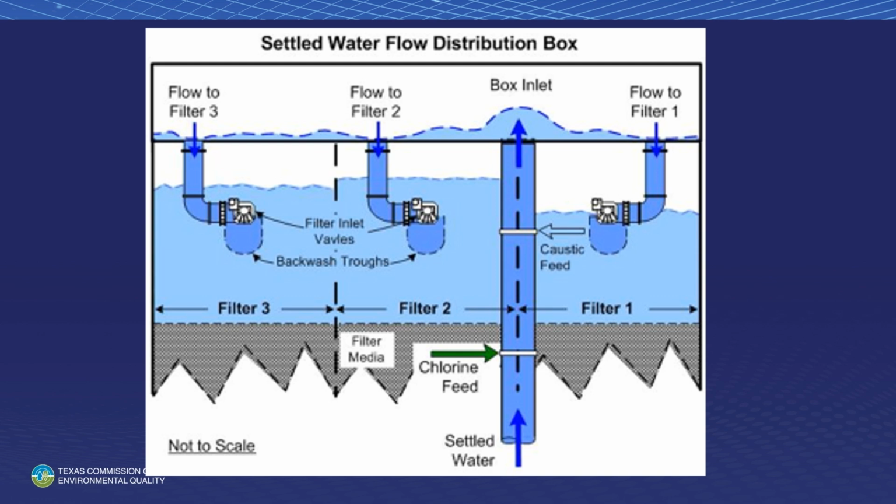Well, what does that do to your CT study? It basically takes out that part of D2, whatever that zone was. They lost credit for that because of the no chlorine and no disinfection at the bottom of filter number 3. Again, it's just a point of how critical mixing is.